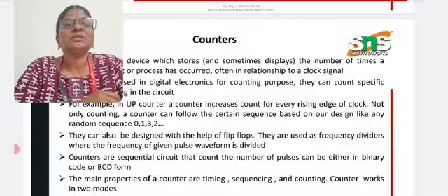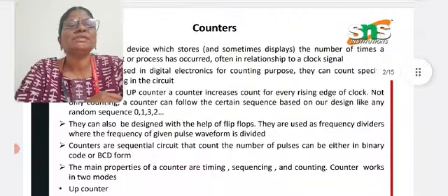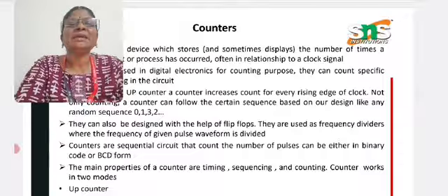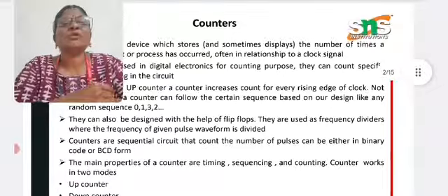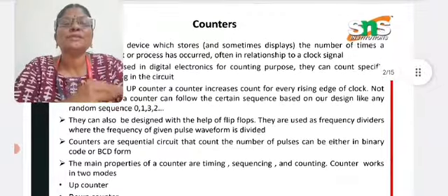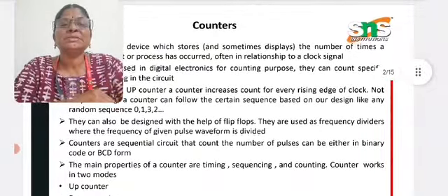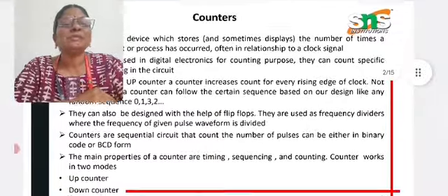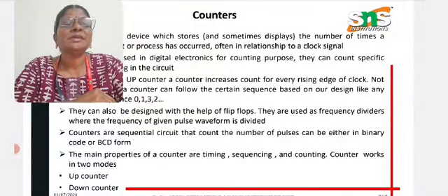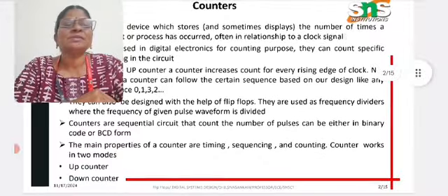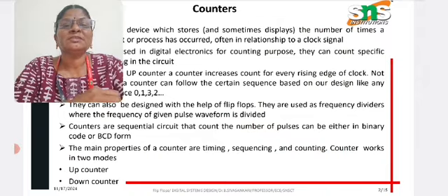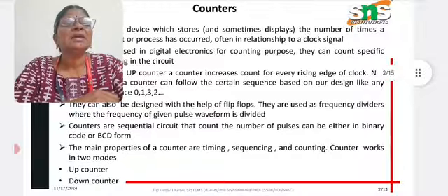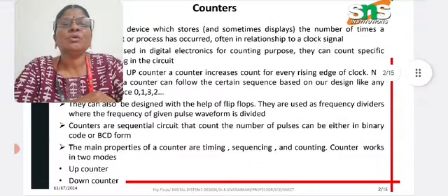Not only counting, a counter can follow a certain sequence based on our design, like any random sequence such as 0, 1, 3, 2. It is not a must that it has to count 0, 1, 2, 3. It may be 0, 1, 3, 2. They can also be designed with the help of flip-flops. They are used as frequency dividers, where the frequency of a given pulse waveform is divided. Counters are sequential circuits that count the number of pulses, either in binary code or BCD form.